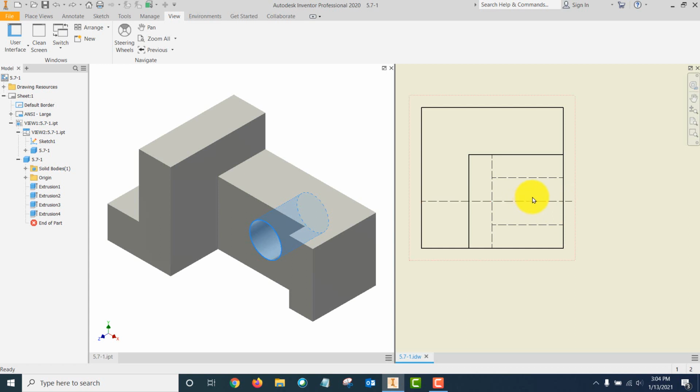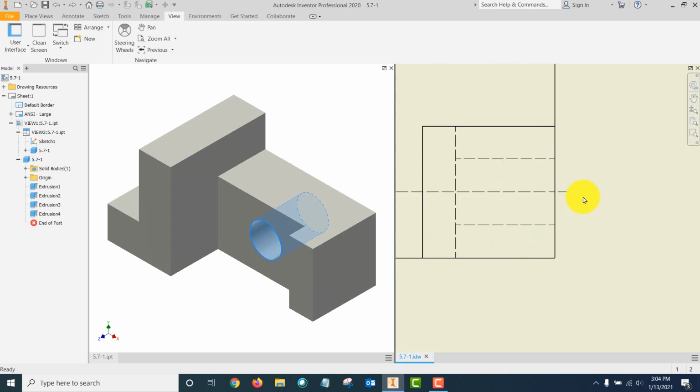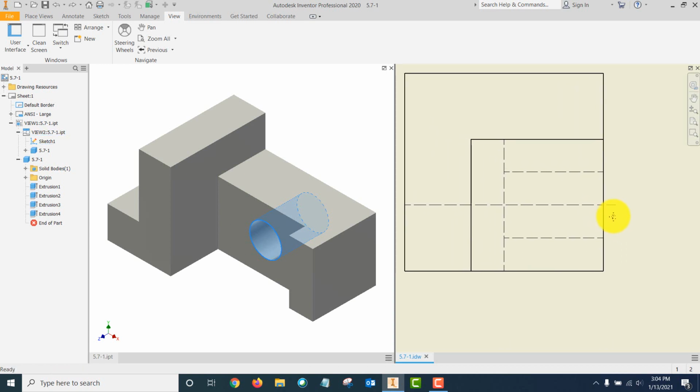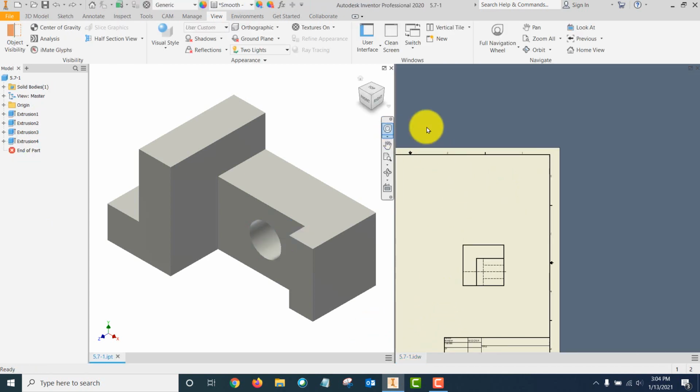Okay, but in a case like this, and we're not doing drawings yet, so I'm not going to get into that. I just want you to know that in the drawings in the textbook, you may see a little dash extending out beyond the object. That is not an extension of a hidden line. That is a center line.